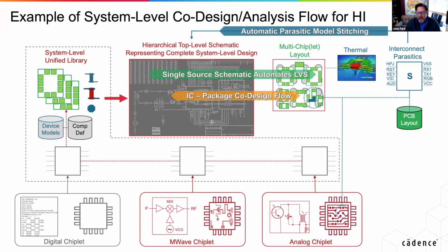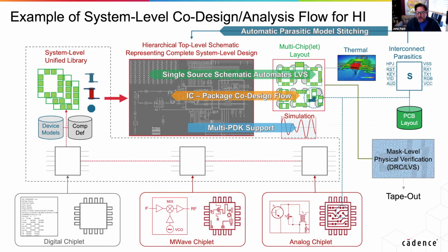So you have to have access to the EM tools that I talked about, that can work on chip, off chip, full system level, extract those layout parasitics and feed them back to your golden source of logic, and in this case, the schematic, so that you can simulate accurately the performance of your multi-chiplet solution. Of course, you can't forget the board in that, and then being able from that platform to build test benches and simulate the functionality of your system. And then last but not least, being able to take the layout data and do sign off with a physical verification tool.